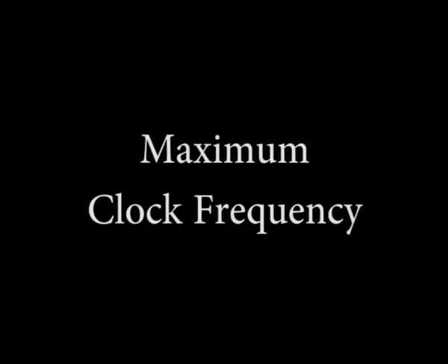Maximum clock frequency. The maximum clock frequency is the highest rate at which a flip flop can be reliably triggered. At clock frequencies above the maximum, the flip flop would be unable to respond quickly enough and its operation would be impaired. Pulse width. Minimum pulse widths for reliable operation are usually specified by the manufacturer for the clock, preset and clear inputs. Typically, the clock is specified by its minimum high time and its minimum low time.